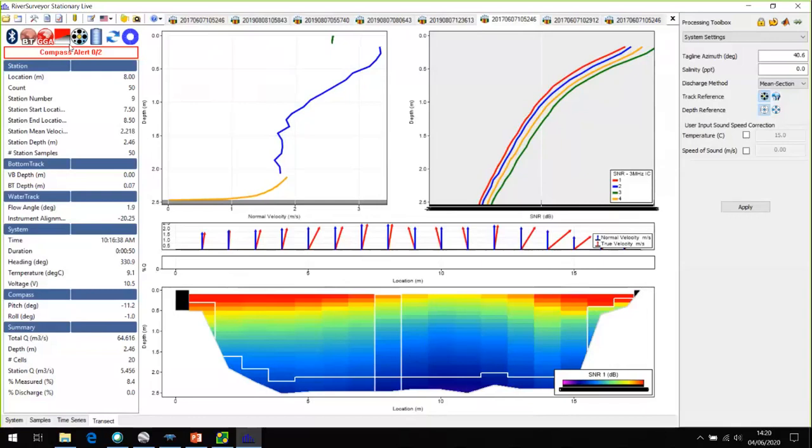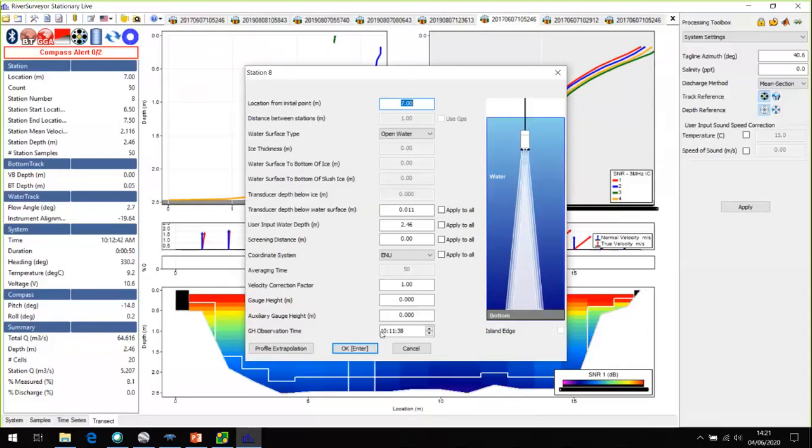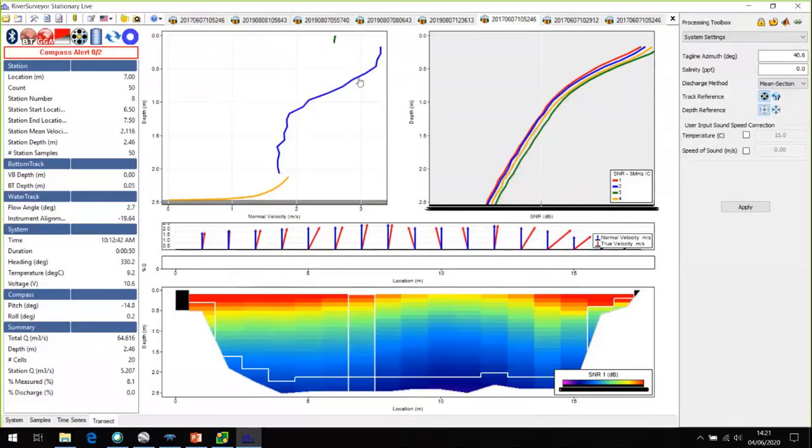So at this site, there's only two ways of correcting this data. One is when you're on site, make sure the pitch and roll is generally less than 10 degrees. You should be okay. Or there's a fudge that Rob does, which is quite cool, to rescue this data. So, do you want to go through that, Rob?